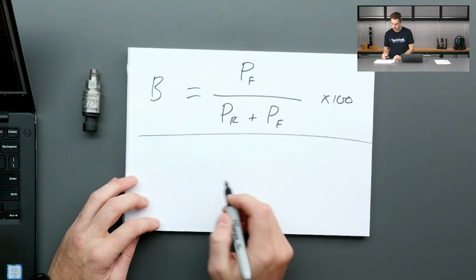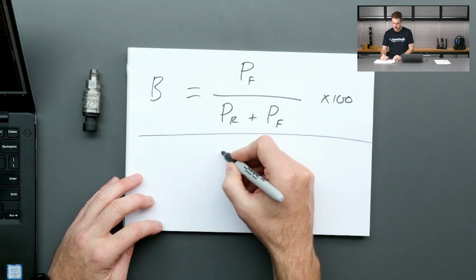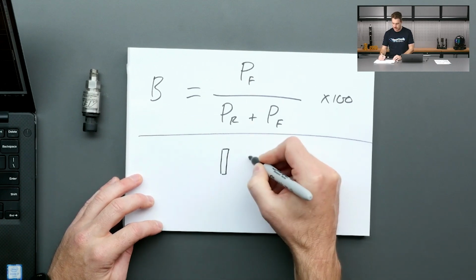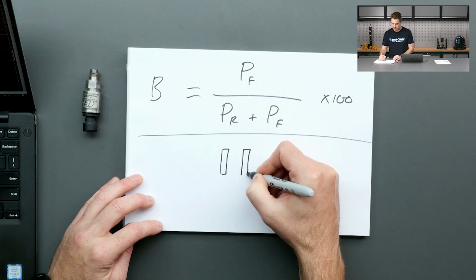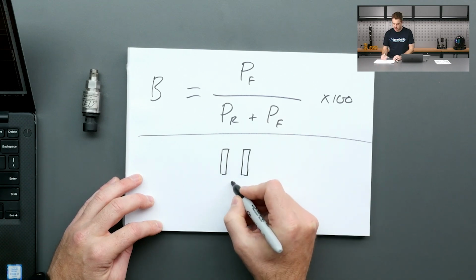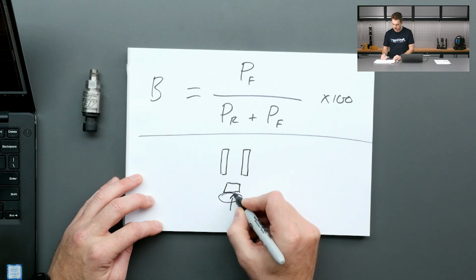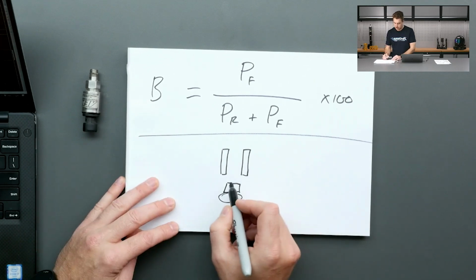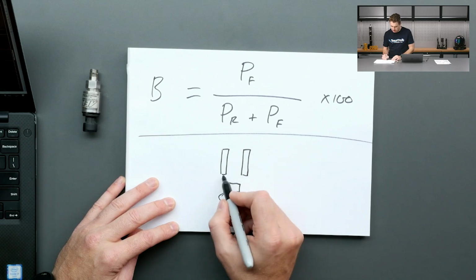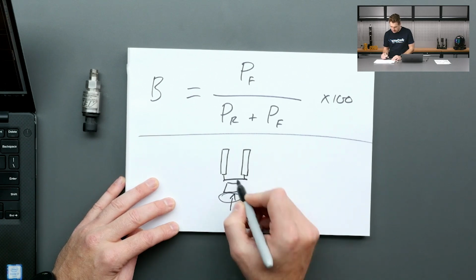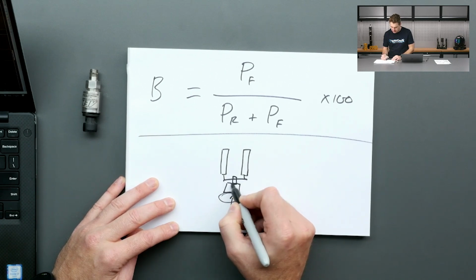Maybe I should talk a little bit about how the brake bias is actually adjusted and why we're measuring a pressure difference as well. So I'll sketch out exactly what's going on there. Looking from the top view of the pedal box, let's say this is the top of our brake pedal, where the driver's foot would be sitting, pressing the brake pedal in towards the master cylinders. You've got these little levers sticking out with a bias bar set up in here.